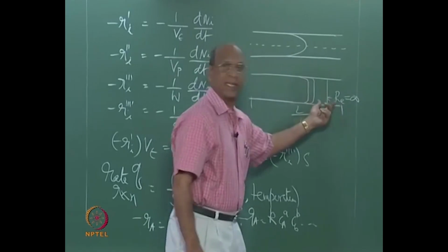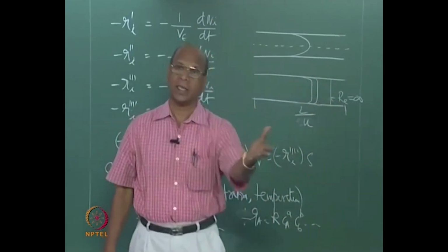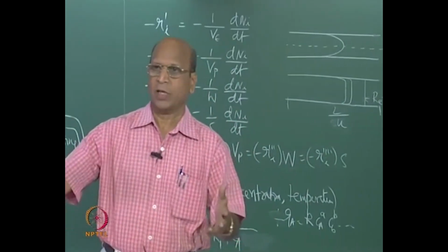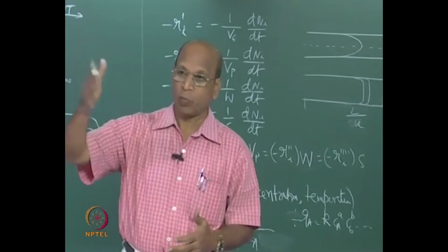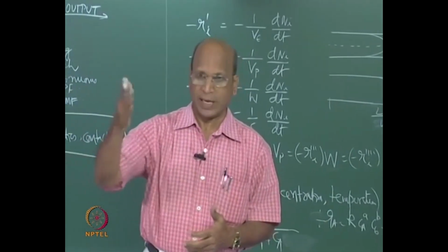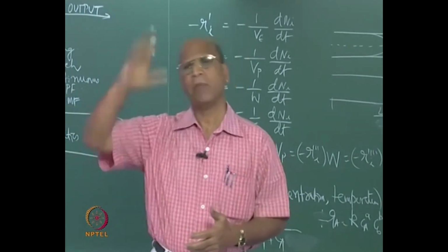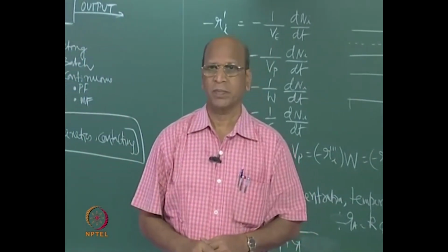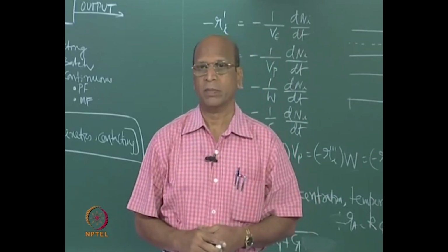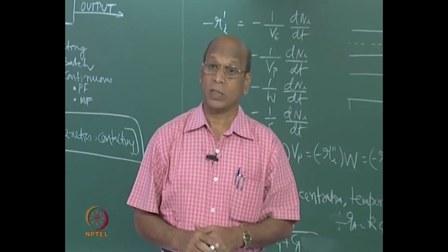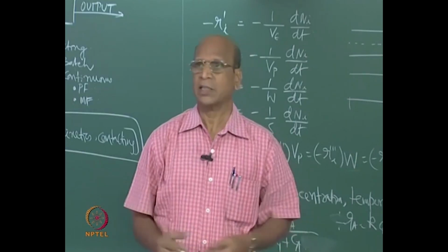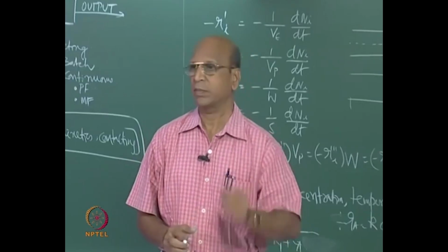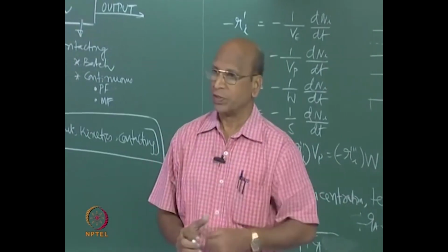when you want to maintain plug flow, you need very high Reynolds numbers. Theoretically you cannot go to infinity, but you need very high values to maintain ideal plug flow. That means you should use very high velocities, and if the reaction time is 10 hours, then what is the length of pipe you require? There are many reactions with 10 hours, and no gas phase reaction takes 10 hours, it is only 10 seconds; 10 hours is liquid phase.